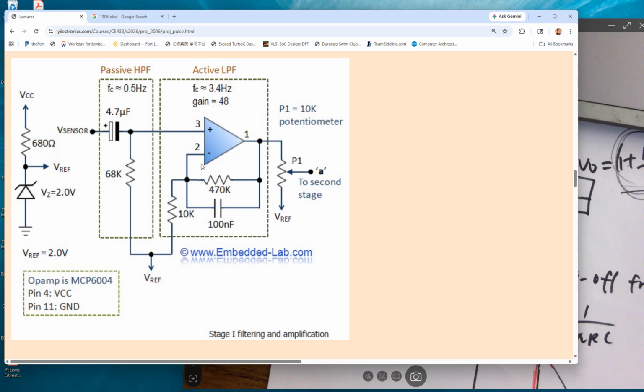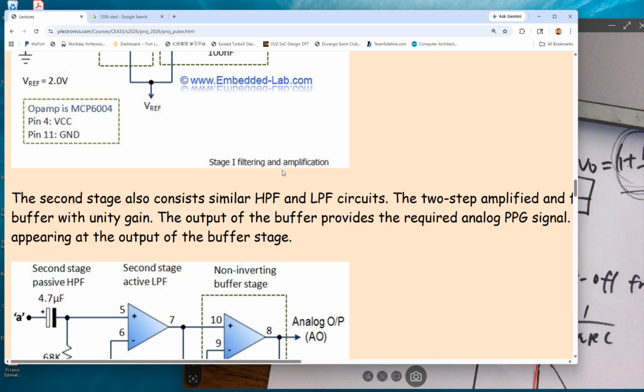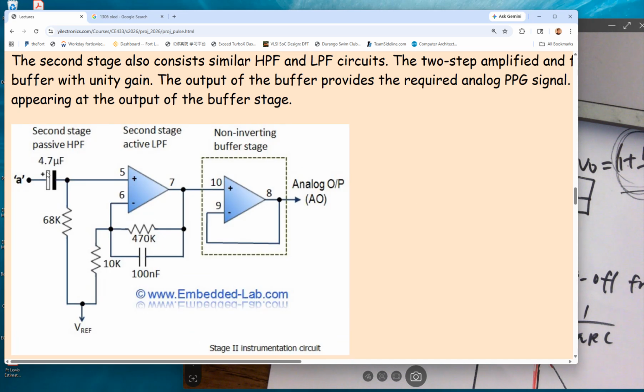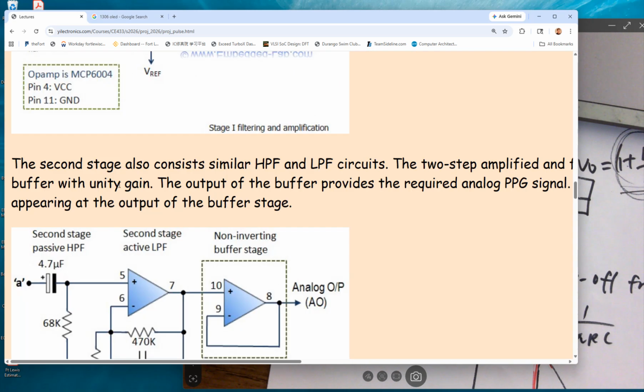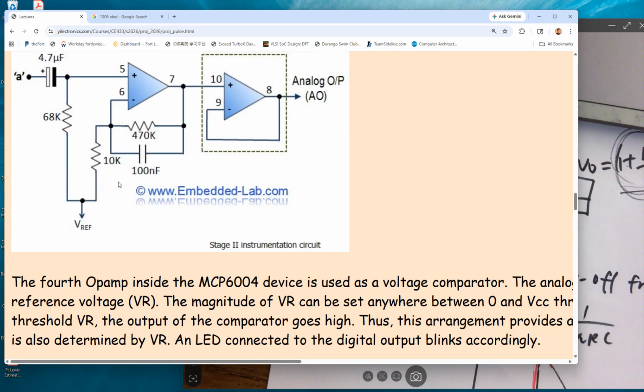So what you do is you amplify a reasonable amount, and then you got a clean signal with less noise, and then you filter everything again to get rid of the noises with another stage, and then you got a cleaner signal to noise ratio, right? And then you amplify it twice. Usually you can see this signal is probably not too weak. I can imagine it's probably tens of millivolts, but some of the signals are lower than 10 millivolts, and you may need like 3 or 4 stages.